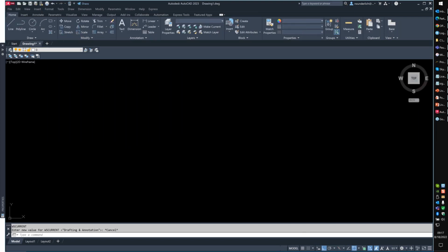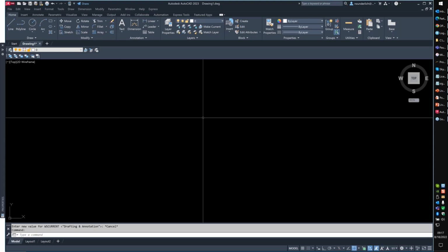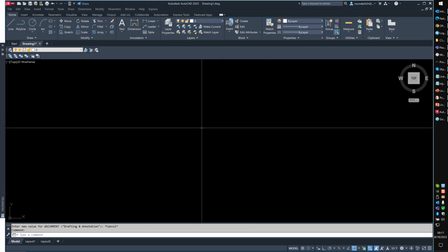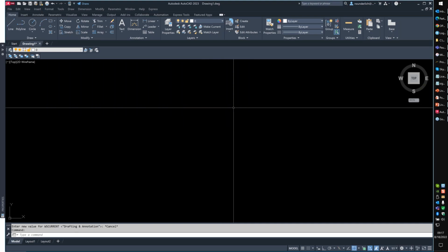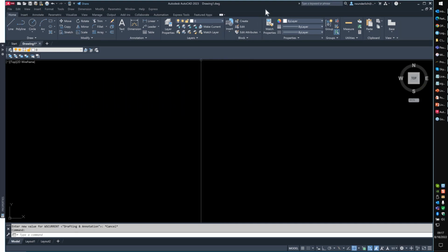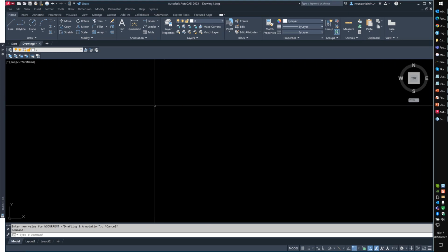But that AutoCAD DWG launcher, this is common. So only keep one version on your machine. You don't need to do that. Beirut, you can keep any version you want on your machine. And I have multiple versions. I have 2017 all the way through 2023 of AutoCAD. Just know that the last version I double clicked and opened from the icon on the desktop. If I double click on a DWG file, that's what it's going to default to.